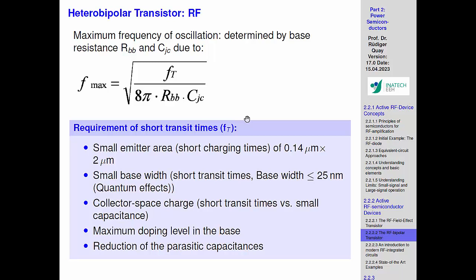But it's fun to work on this. It keeps you, if you're just up in front of the world's development, that's interesting. And by the time, the frequencies which we reach at the moment are at the terahertz regime. So it's not gigahertz anymore, but we are one step up. So the highest stuff we have access to. The fastest FETs we can make at the moment have an Fmax of more than 1 terahertz. So they still provide power gain at terahertz frequencies. That's really the forefront of research.